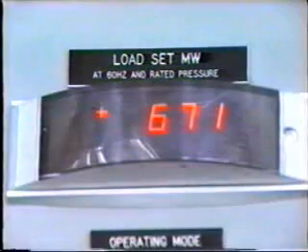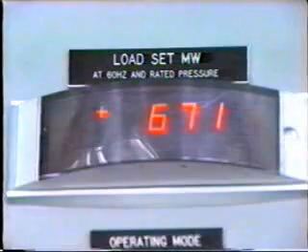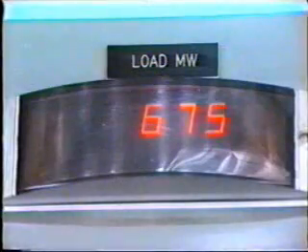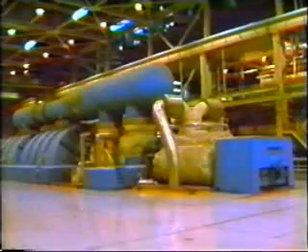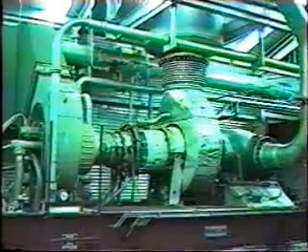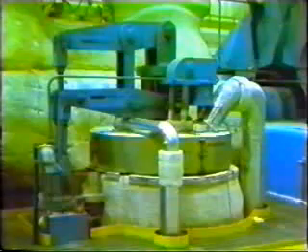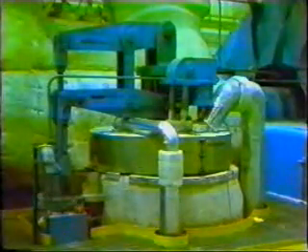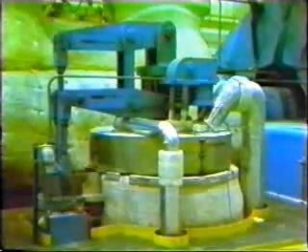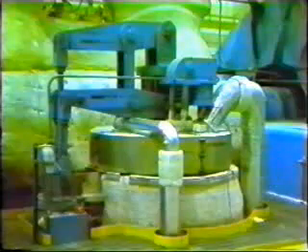Adjustment of the turbine governor's set point regulates the mechanical energy input to the generator and consequently determines the electrical output. This situation is the same whether the generator is driven by a steam turbine, gas turbine, or a water turbine. It may take several seconds for governor adjustment to achieve the required change in generation, but this is quite adequate for normal minute-to-minute variations in load demand on the system.